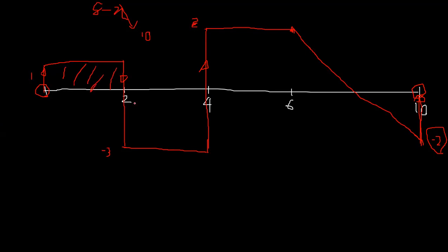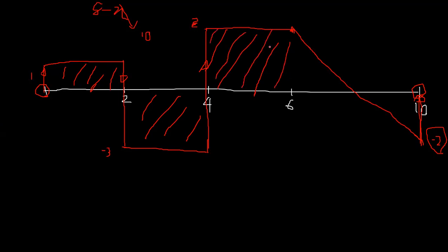Within these methods, it's very easy. If you have a point load, there's a sudden change in shear, but no change in shear if you don't have any load within the beam. If you have a gradual loading, that means a collection of point loads, so a collection of sudden changes, gradually changing, and this would look like this.